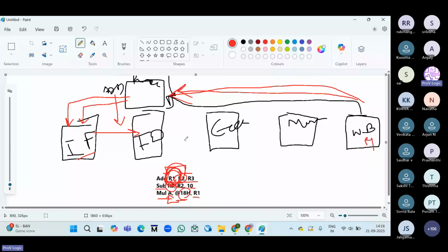After decoding the data, it will go to the execute stage, because whatever we are writing here uses the ALU, arithmetic and logical operations, right? Mostly jump type or branch type, everything will be arithmetic and logical operations. So there will be an ALU in the execution stage. It performs the instruction execution according to the operation we have written. It calculates the address for the memory access.